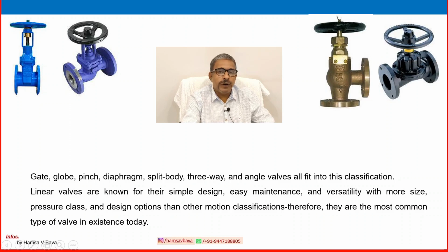If time permits, visit your field. Next time you visit, look at the various valves and understand them with the P and ID. See what the different symbols are, and in the field identify physically how each one is and what the differences are. That will give you a very good experience in understanding valves.